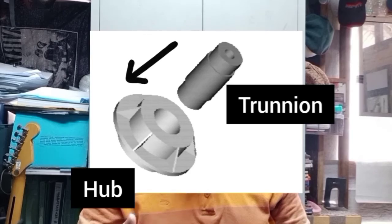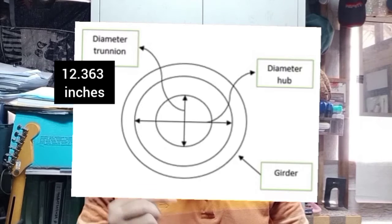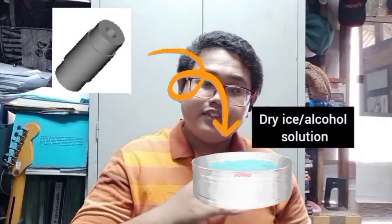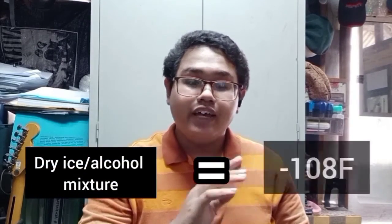Okay, so what do we want to solve in this assignment? Michael is one of the designers for the new construction of a bascule bridge, and he wants to make a fulcrum for the bridge. However, Michael has faced a problem in his design where he needs to fit a hollow trunnion of outside diameter 12.363 inches in a hub of diameter 12.358 inches. His plan is to put the trunnion in a dry ice/alcohol mixture. The temperature of the dry ice alcohol mixture is -108 degrees Fahrenheit, to contract the trunnion so that it can be slid through the hole of the hub.